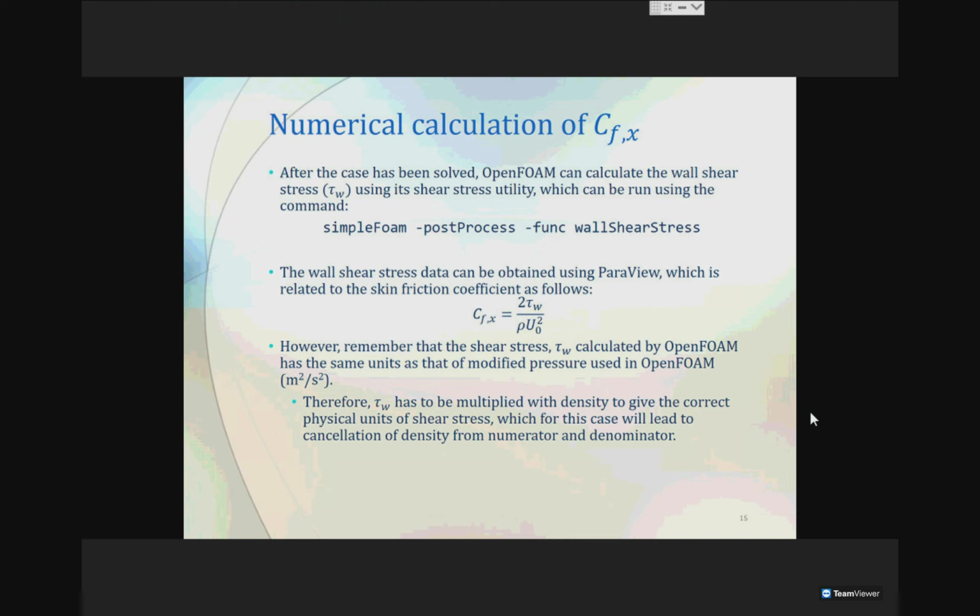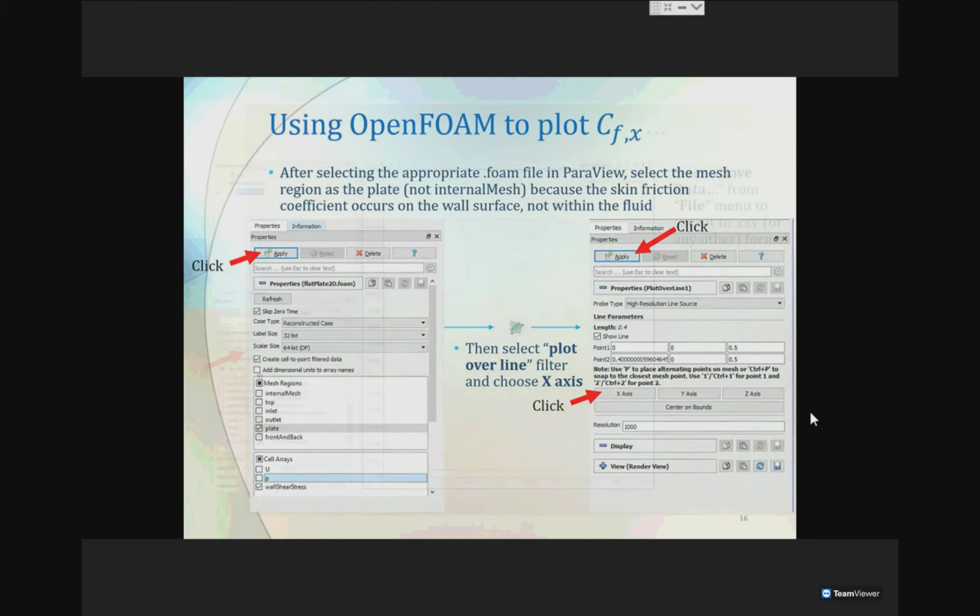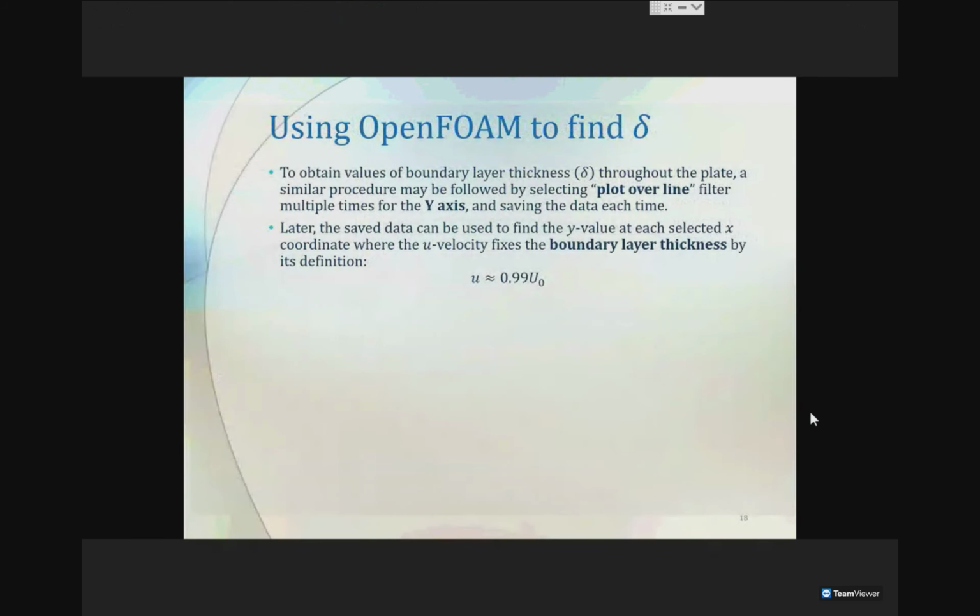Okay, so while doing the calculation, I have also described all of this on this slide. If you are not understanding me verbally, you can read through this later on. So this is how you generate the skin friction coefficient plot. Now, how do you find the thickness, the boundary layer thickness on your plot, on your graph, or on your figure?